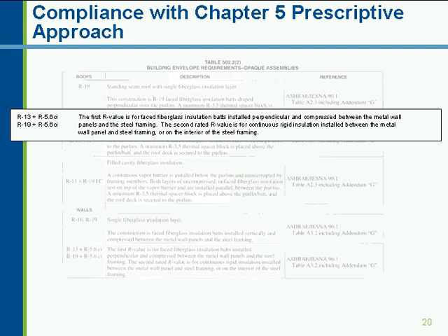So again, this will give you the ability to determine how to install the insulation and give you a full description on how to do that. So the R value table will tell you how much to put in, and this will tell you actually how to install that insulation. The other option you have for metal buildings is to go into the assembly U-Factor table and generate an assembly U-Factor for either your wall system or your roof system and meet those requirements instead of going into this R value table.